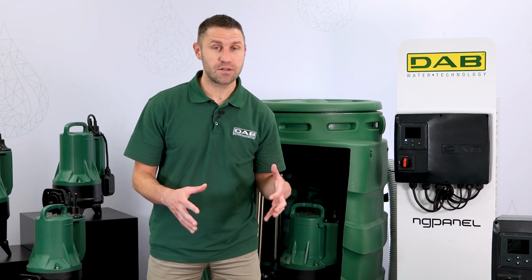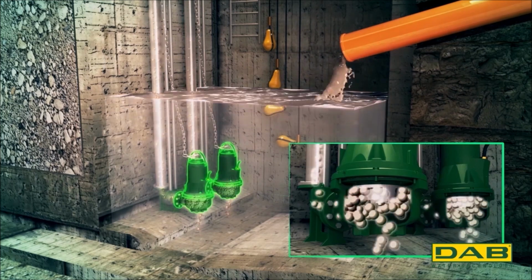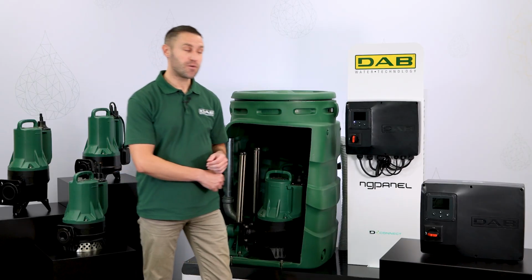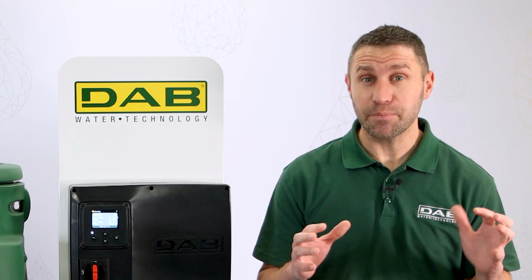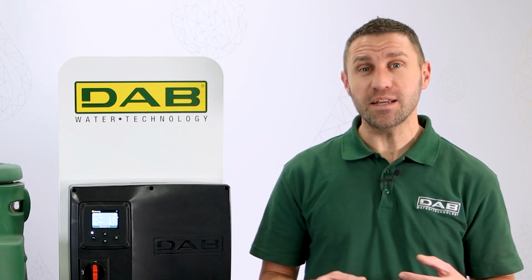In this configuration, we want the pumps to start when the destination tank is almost empty, and we want the pumps to stop when the destination tank is full. First of all, we need to select the option for filling on the display. Since this is a big choice that changes the logic of the system, we need to configure some important parameters.